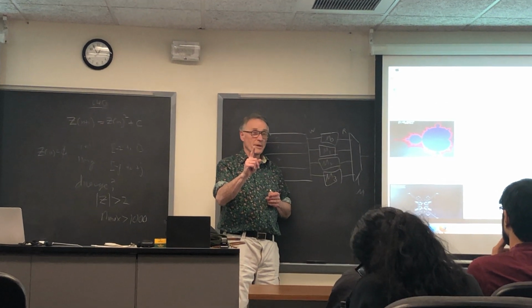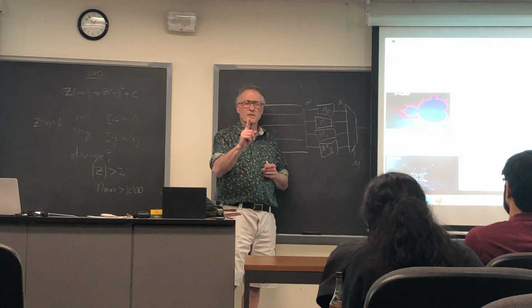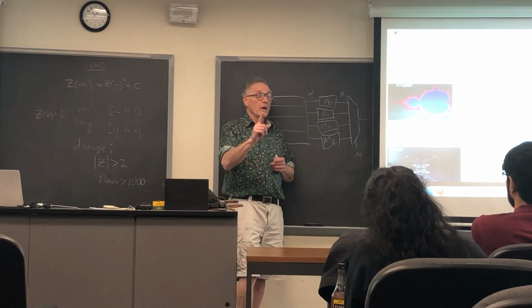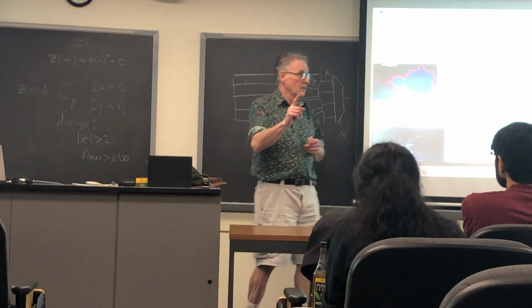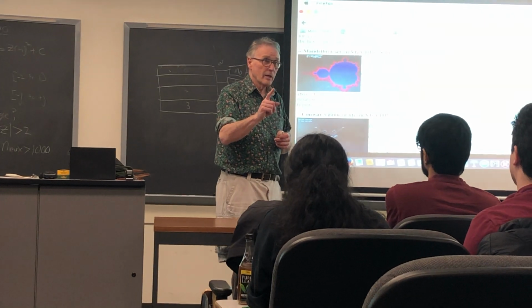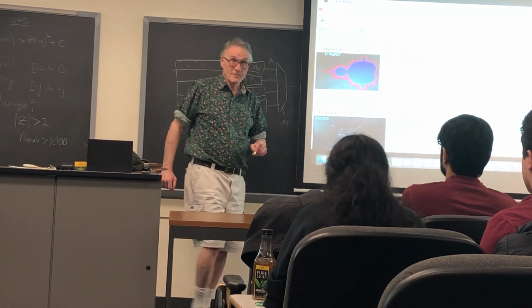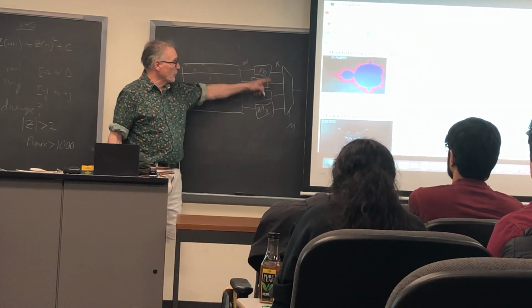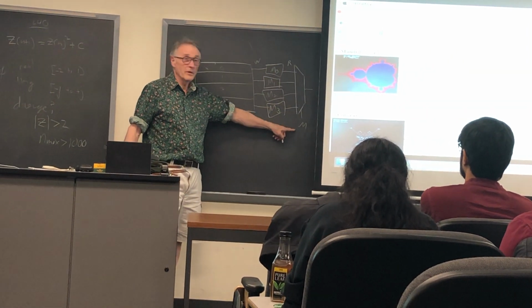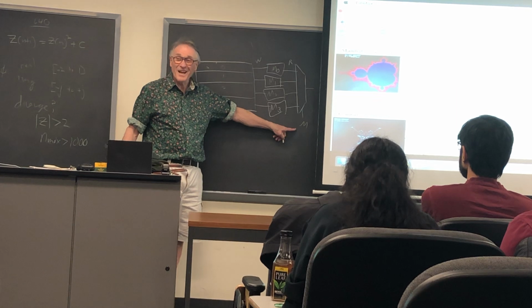VGA runs at 25 megahertz, 25.125 megahertz. You can't wait for the pixel. VGA has no memory. It wants the color when it wants it. And that's the huge advantage of the dual ported memory, is the controller can read the memory anytime it wants.